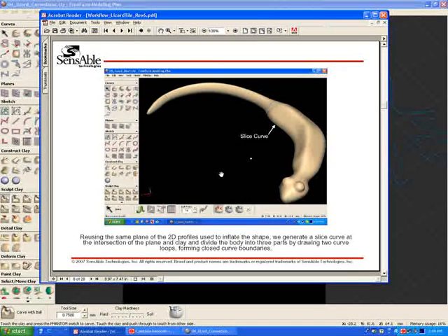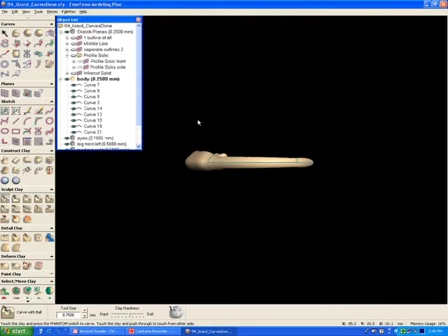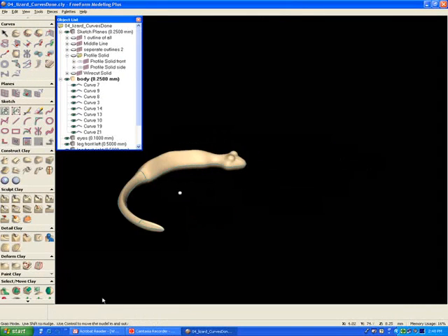What's now prepared in this file is that I have used a slice plane, which enables creating a curve on the object wherever a plane is intersecting with the clay. So that is how this curve has been drawn, and the top curve have then been drawn using the draw curve tool directly on the clay, and by activating fit to clay, these curves will automatically cling to the surface of the clay. So that's the object over here.